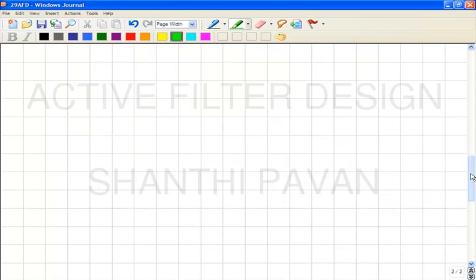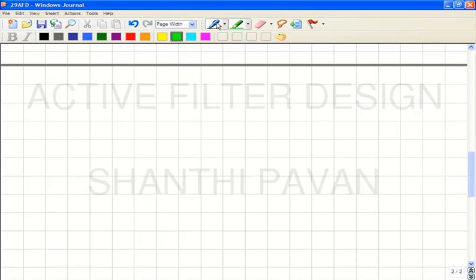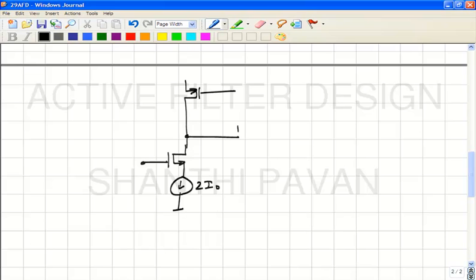Okay, sorry, let me rewind. Let me draw the common mode equivalent so that we don't get confused. This is the common mode equivalent. This is the common mode detector, right? And this is the error amp, which we all understand is a transconductor which is actually pumping current out, and this guy is the compensating capacitor.